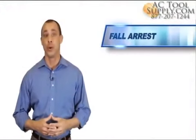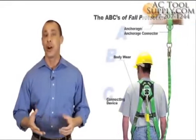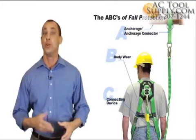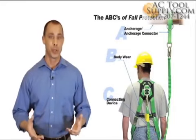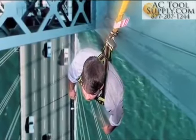Fall arrest equipment, or personal fall arrest systems, is comprised of three components that are often referred to as the ABCs of fall protection. These are anchorage connector, body wear, and connecting device. Used properly, a fall arrest system does not prevent a fall, but rather suspends a worker in the event of a fall and prevents impact with a lower obstruction or the ground.